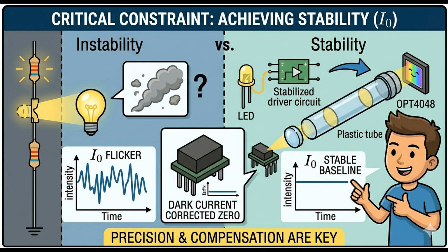So flicker is one thing. If it's not aligned, you have to have good precision current control on your light source. You have to have a good sensor with multiple readings and averaging those readings. To get it to work requires a lot of work, so that it's not creating a lot of strange data.